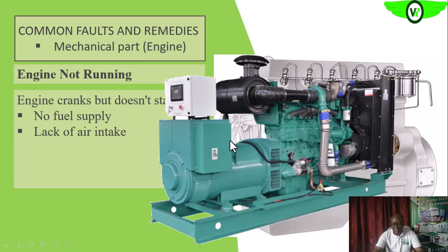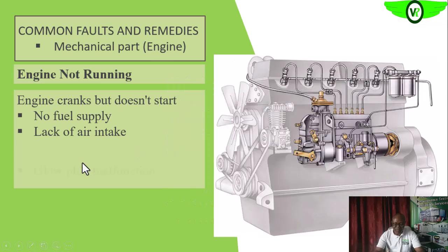Or if the turbine section is also faulty, which means that the drive force will be small compared to what is required, that will affect the amount of air that is administered into the combustion chamber. Then if we have a heater plug on the diesel engine, remember in some instances we need to heat up the cylinder, the combustion chamber, raise the temperature by turning on the heater before we start the engine.